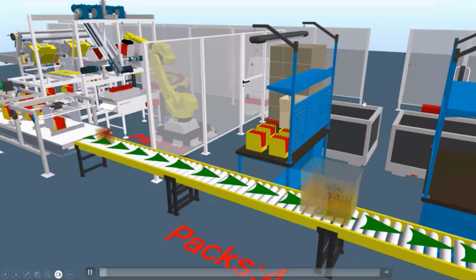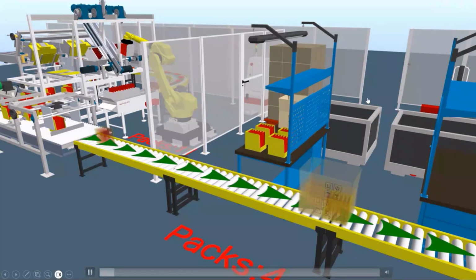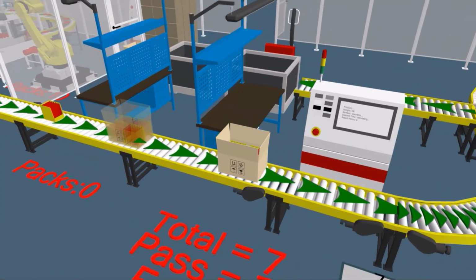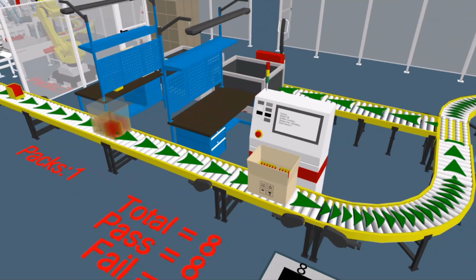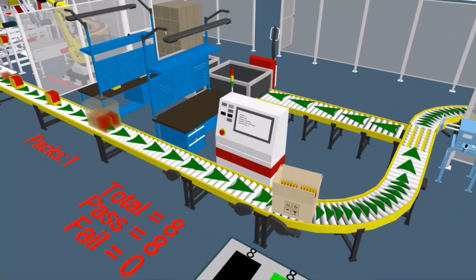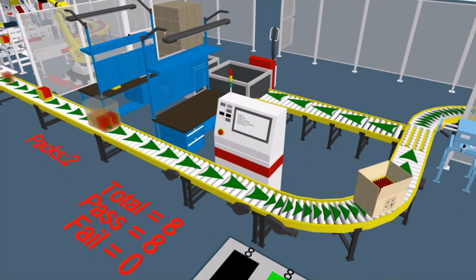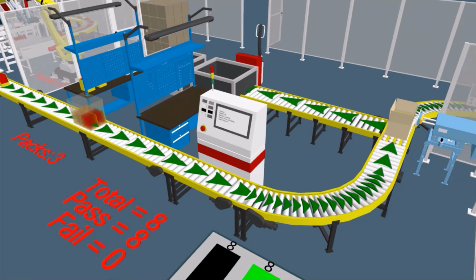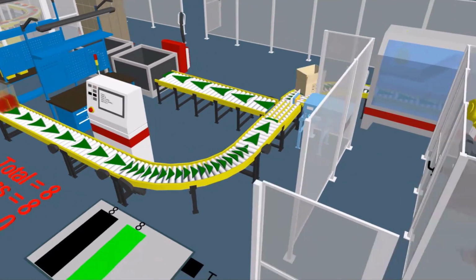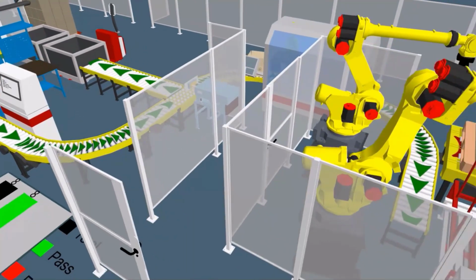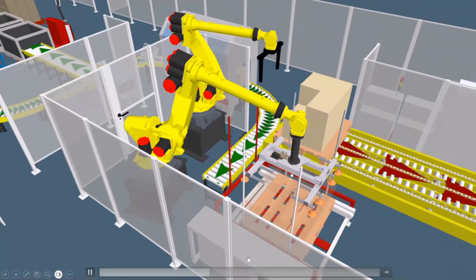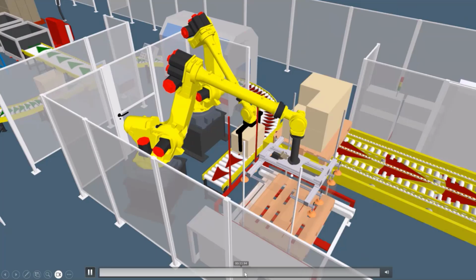Or maybe you want to simulate your machine's operation time. In this case, we want to pack, maybe boxes or packaging machines. How long will it take from one station to another to complete a full box of, maybe flour or sugar, for example. So you can simulate that in real time, and plan how fast the movements are.